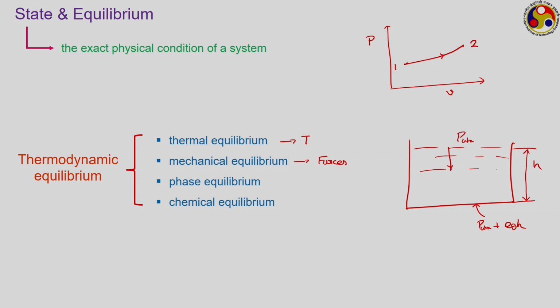That is why the terms quasi equilibrium or quasi static are also commonly used. So, state 1 is an equilibrium state, state 2 is also an equilibrium state, and all these intermediate states may not be in perfect equilibrium, but they are in quasi equilibrium condition, that is, they are very close to an equilibrium state. So, your entire study of thermodynamics was based upon this concept of thermodynamic equilibrium,